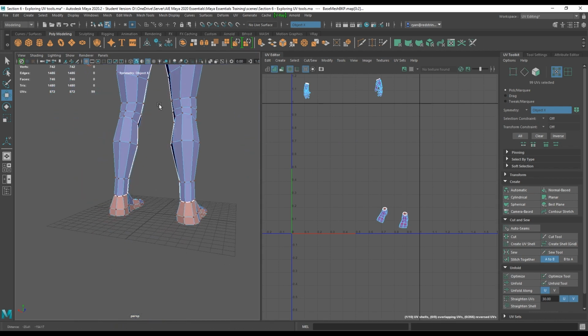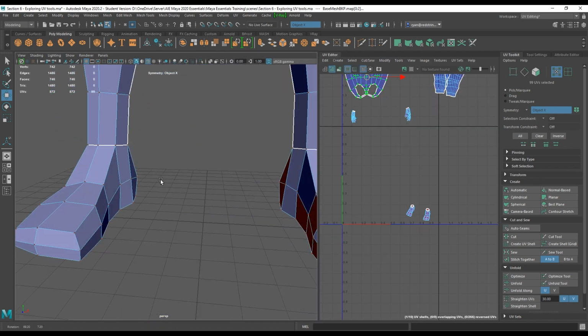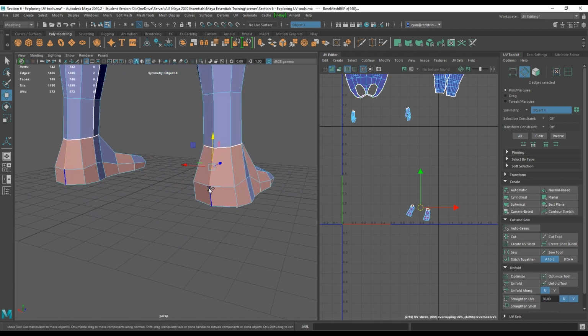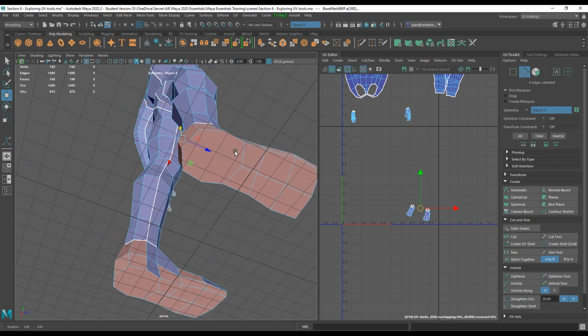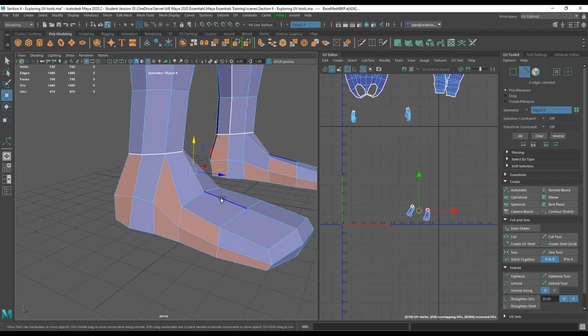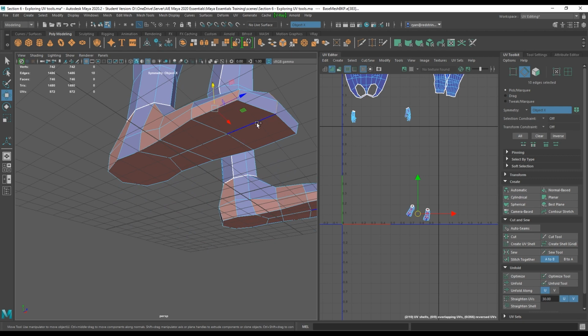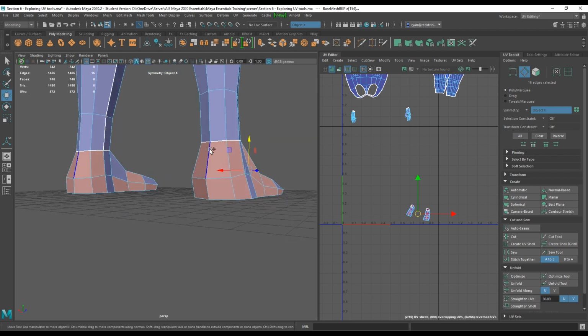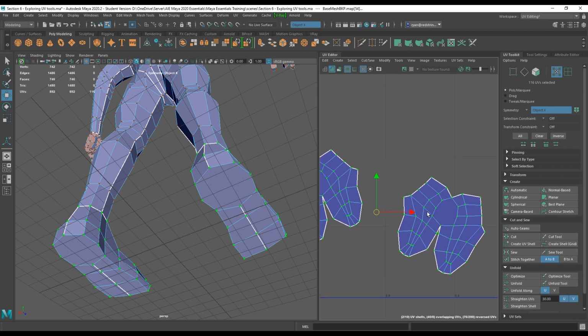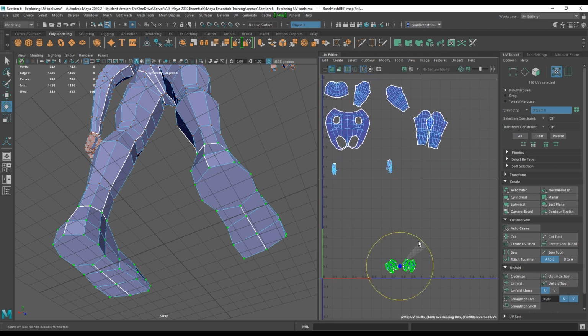Now let's go look at the footsies. Let's make this space a little bit smaller. Okay, so what we can do with the footsies potentially is have the edge come down the back of the heel. There's a big giant N-gon, which is going to make our lives a lot harder than it needs to be. Maybe let's take it down the front of the foot. And then take it there, there, and there. And then I would need to open up the back as well. Let's go to cut, right click, UVs, and then go unfold. You can see here, they look pretty decent. But here you can see the problem now with N-gons and triangles and stuff. It doesn't optimize your UVs quite as well as having all nice square topology.